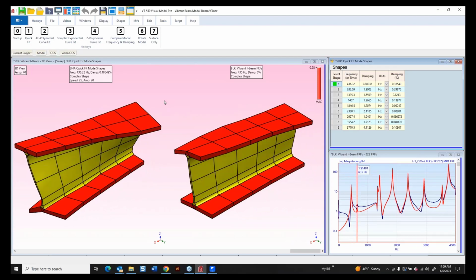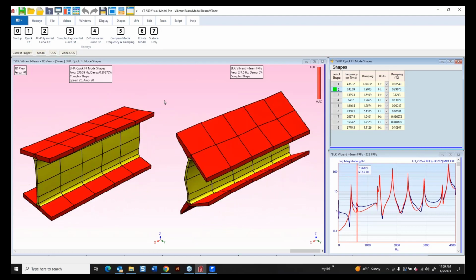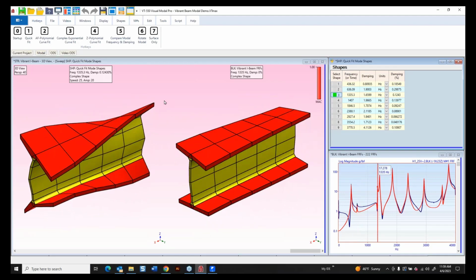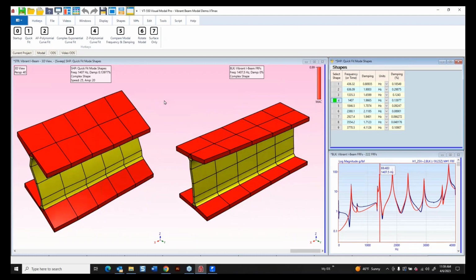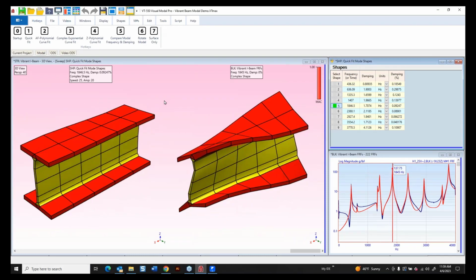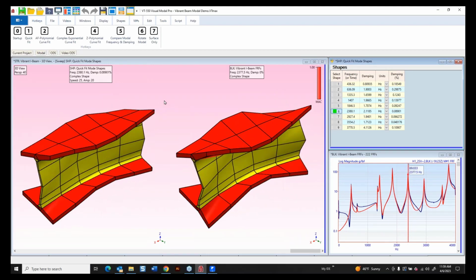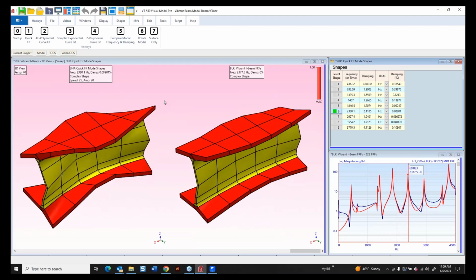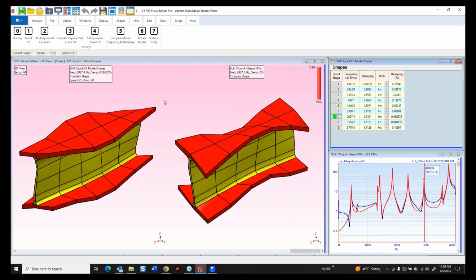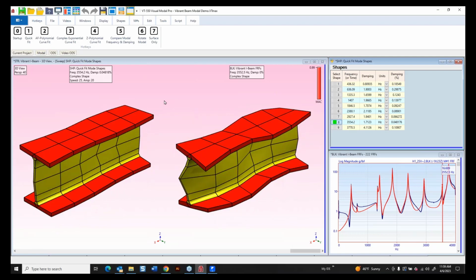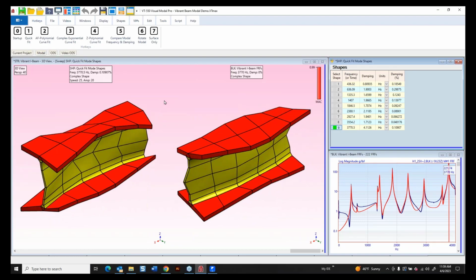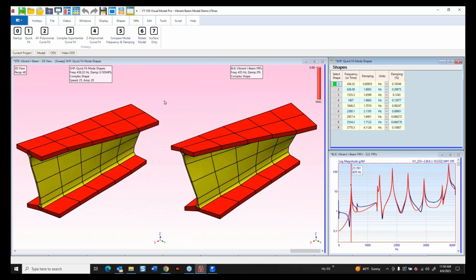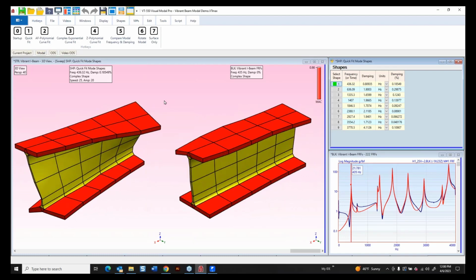Now, we'll look at impulse responses next time, and what that means is it's really a negative value, but we call it positive modal damping because the damping has to do with the envelope of the response of each mode, and if we look at the mathematics, it's actually a negative number because the envelope is damping down the vibration as we increase in time of the impulse response. So I'm throwing out a lot of words here, but the quick answer is no, the curve fitter shouldn't be giving you negative damping. It should be positive.